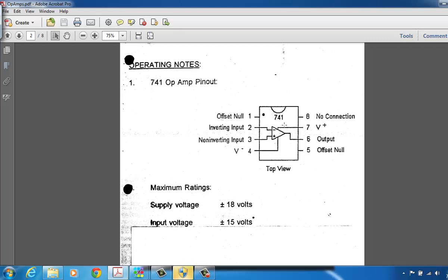It will overheat, and if you have it hooked up backwards long enough, it would actually start to smoke and disintegrate. So you'll physically damage an op-amp IC, and for that matter any IC, if you hook up its voltage backwards. ICs are voltage polarity sensitive, like we talked about earlier in the course when we talked about the voltage polarity protector using a diode.